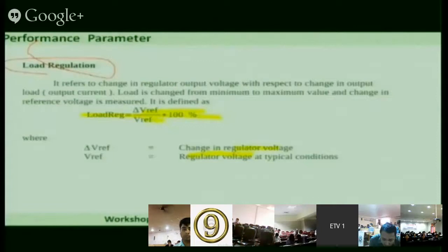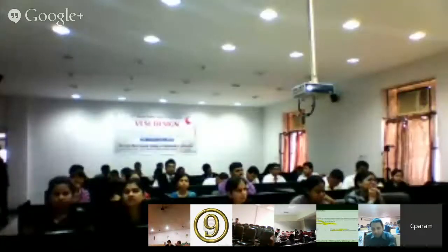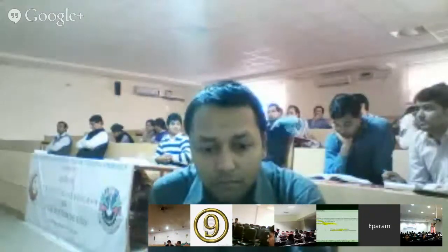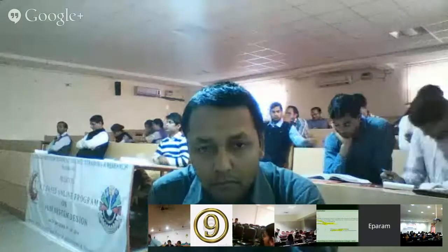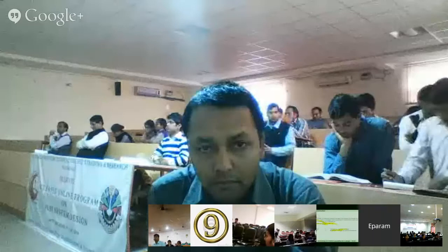Del Vref means how much the voltage has changed if you change the current from no load to full load. So del Vref divided by Vref and into 100, this is the meaning of load regulation.